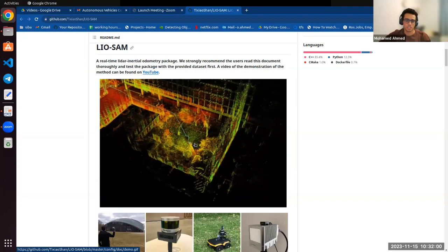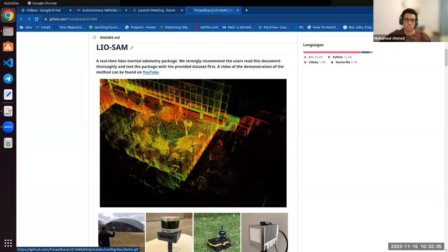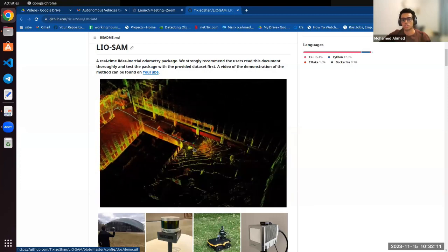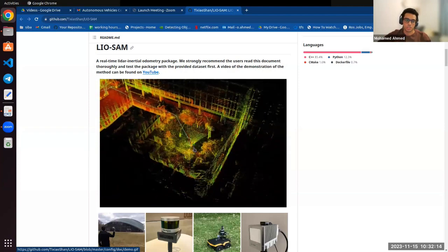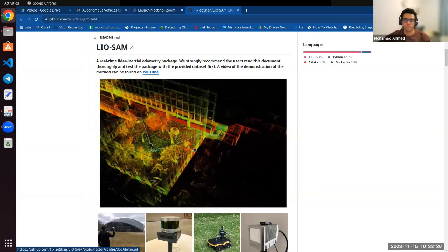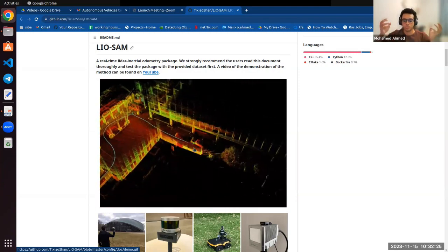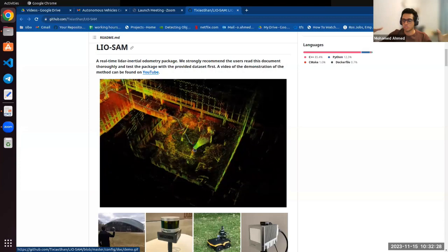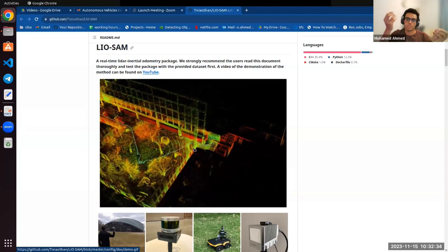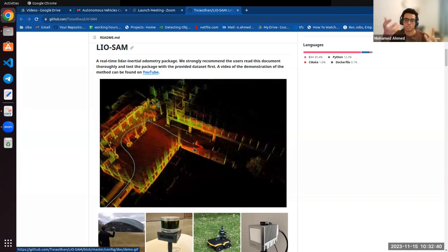As you can see here, there's a robot that keeps scanning the environment, and it updates its map, and at the same time you can see it tracks the position where it is, and sometimes it corrects its position. So this is a very important step for mobile robots in general and autonomous vehicles. So you need to know two pieces of information. The first one is to perceive the world, like you need to know where the obstacles are with respect to you. And the second is you need to know where you are right now. So this is what perception and SLAM are doing.